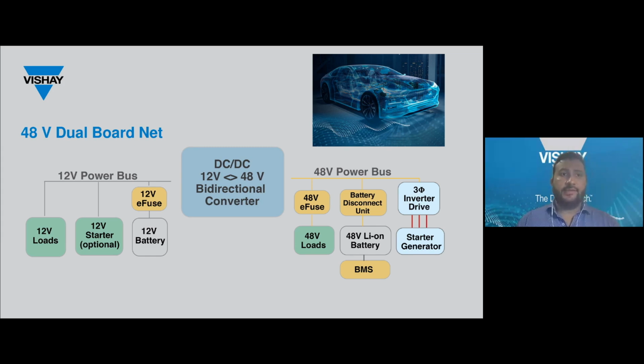Tesla Cybertruck is an example of an electric vehicle that adopted this new architecture that used to be only 12 volts to power various loads from the low voltage power battery. The 12 volt bus is not going away. It's still used to take care of the low power loads such as lighting and infotainment. The 48 comes into play for the power hungry loads like power steering or air conditioning.